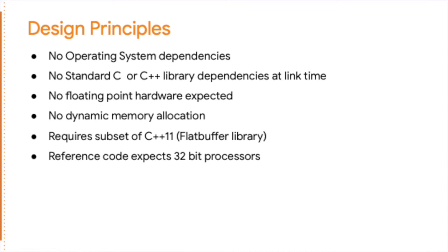No dynamic memory allocation. We do require a subset of C++11, nothing too scary, nothing crazy with templates or exceptions, but the flat buffer library we rely on does need C++11, so we've had to work with a few vendors to make sure their tool chains have been upgraded since it's only 9 years old, which is still a challenge for a lot of people.